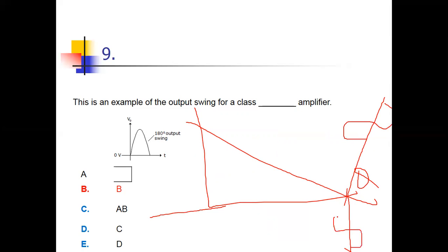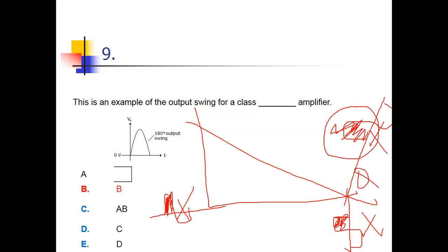Only half portion coming here, up to the load line, and here also only half portion is part of it. Half is clipped, half is clipped, half is clipped. So we are getting the conduction angle up to half only, meaning 180 degrees.